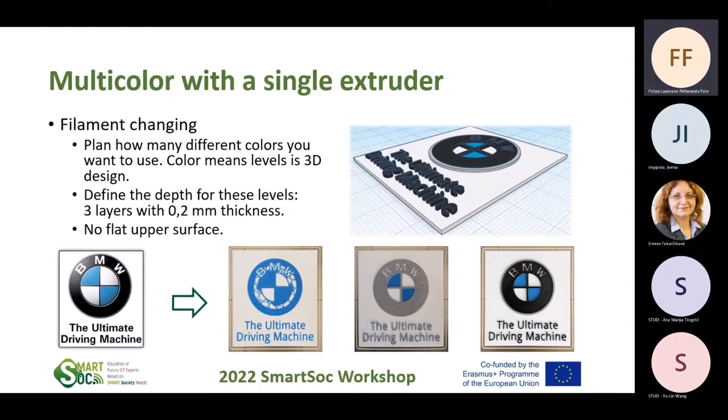Here you should compute with the layer height. On the table you can see green samples. They are in one layer. It is 0.2 millimeters. This is the typical layer height, very thin. It is the usual layer height in this technology. So when you compute different levels in your design, you should compute with the layer height 0.2 millimeters, and you can touch it in the green sample.